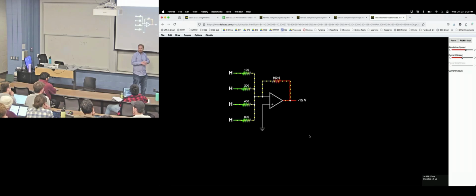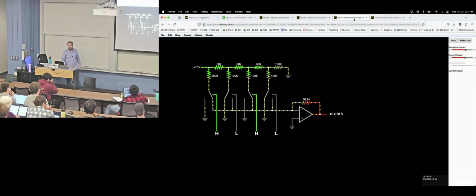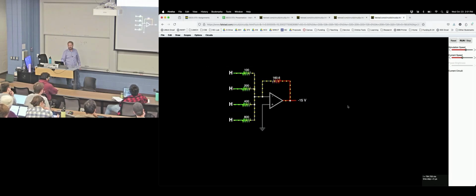Just to explain why this is wrong, why couldn't you just have it go straight out without that whole structure? Wouldn't that just be this thing? I think it would be, it seems like it's about equivalent, right? And then the challenge is, well, now I have to have lots of resistors. And so those tricky analog people are trying to get rid of those resistors, only because resistors happen to be big in silicon. Otherwise, nobody would care about this problem. They'd just use all the resistors they could get their hands on.